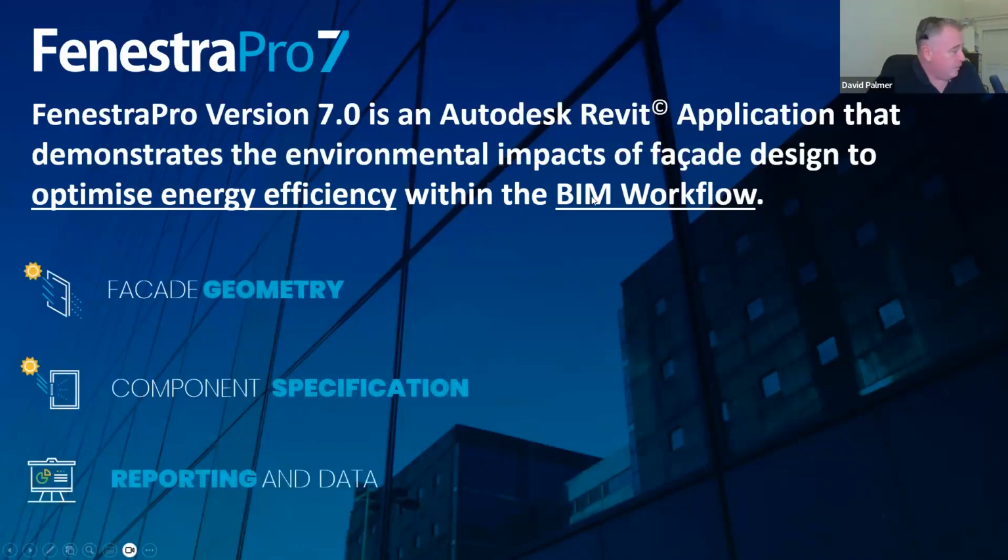Again, we talked about facade geometry, your percentage glazing, distribution, configuration of glazing. So the facade geometry is one of the things that we look at, and component specification. That's the materiality aspect of it, where we look at the various considerations associated with the wall performance, and typically that's driven by U value. With your glazing performance, you're looking at things like solar heat gain coefficient, visible light transmittance, and of course the U value.